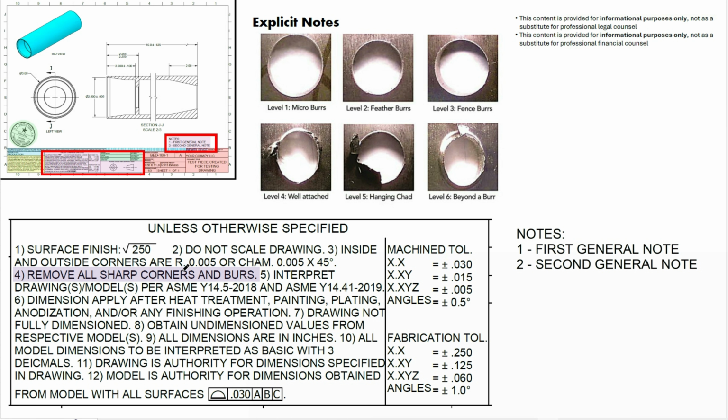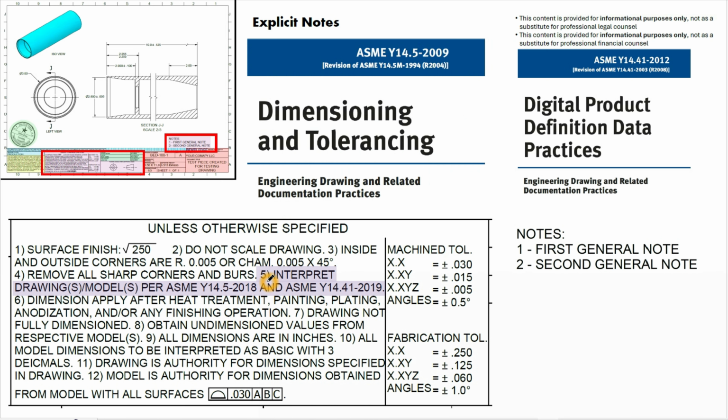So what you're telling them is that, look, even though maybe your dimension is perfect and your chamfers are right, I still want you to go and deburr these, because this is a legal liability. People can get hurt if the parts reach the customer, someone cuts their finger, God forbid they hurt their eye, or even the people in the shop handling this product could get hurt or cut. So you're telling them, please take care of that, and it's explicitly stated.